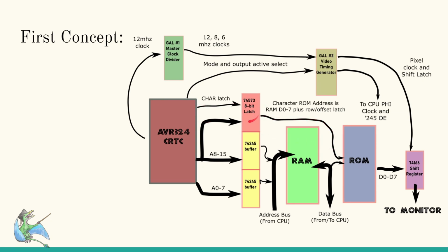But if you latch it, then whatever value was on the input lines when the latch was triggered will be stored in some flip-flops inside of it, and that will stay. It's basically a 1 byte memory that'll stay in there until you release the latch and do it again.